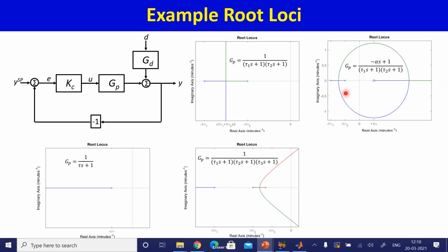So if you have to draw the root locus, if you just think about it, you start from where locus exists on this part, so therefore as kc is increased above 0, this root moves that way, that root moves this way. There comes a breakpoint, and then if you increase kc further, you break out into the complex plane. The locus breaks out into the complex plane, and 0 acts as an attractor.